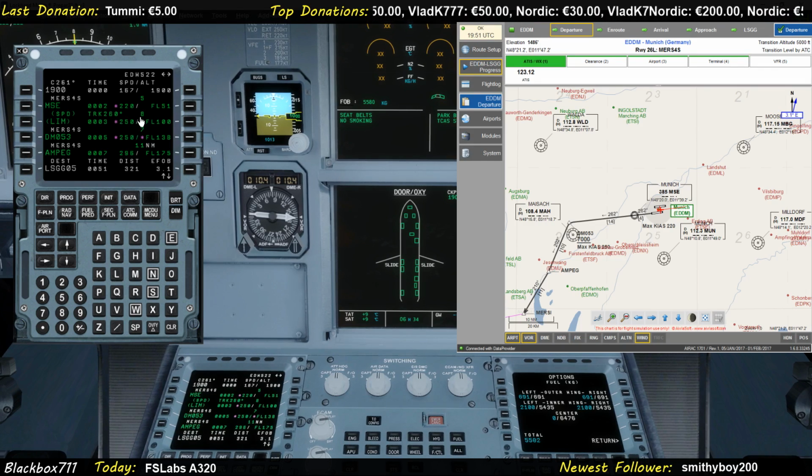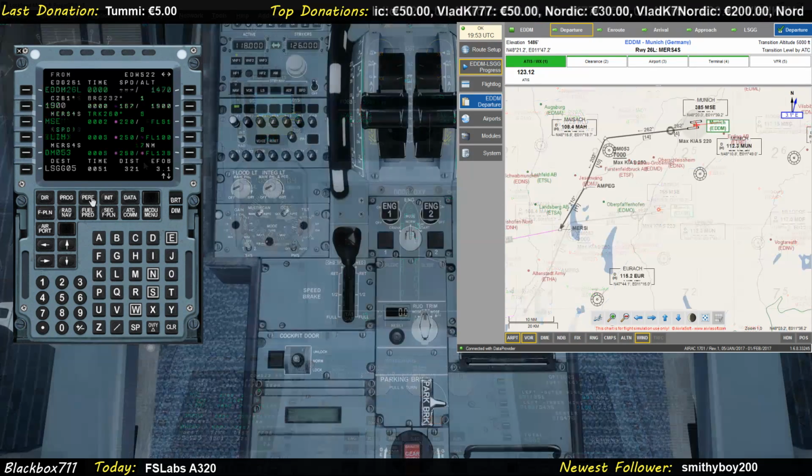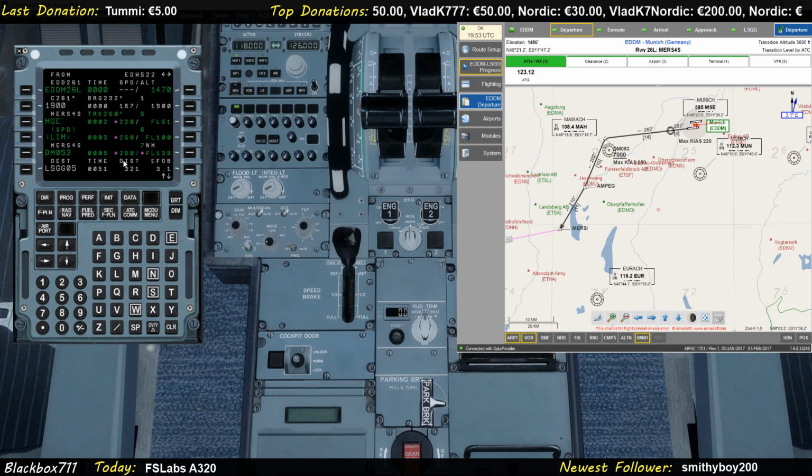So in the departure route, you have to make sure that the coding in the FMS coincides with the chart. And so the chart that you have available and is current, that is master, unless it says something else in the NOTAMs, notice to airmen, which you also have to check. But if there's no change in NOTAMs, then you have to make sure these restrictions are actually correctly programmed in the FMS.